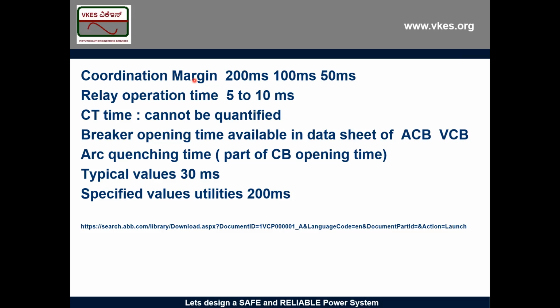Okay, that is good. And Mr. Inamal, what is coordination margin? Coordination margin, I think, is the time gap, the difference between two relays, the downstream relay and the upstream relay. Okay, sir, correct.